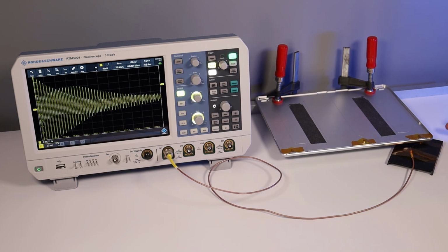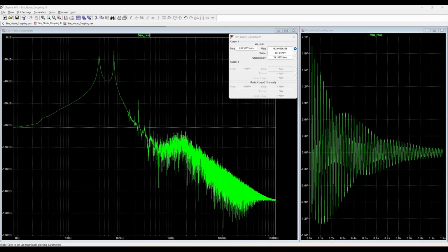Let's do an FFT on that signal and look at the frequency contents. Okay, now we're getting somewhere. We are seeing two peaks, one at 36.5 Hz and one at 76 Hz. The second peak at 76 Hz is our second eigenmode that we've calculated to be 78 Hz. The odd waveform we are seeing is the product of two eigenmodes resonating at the same time.